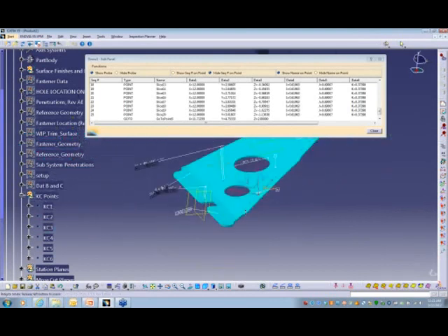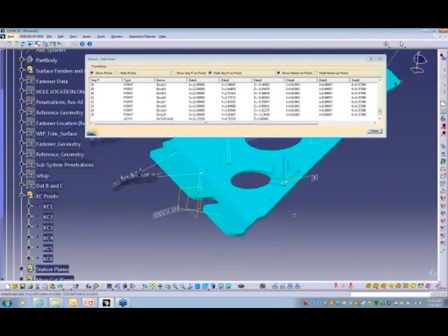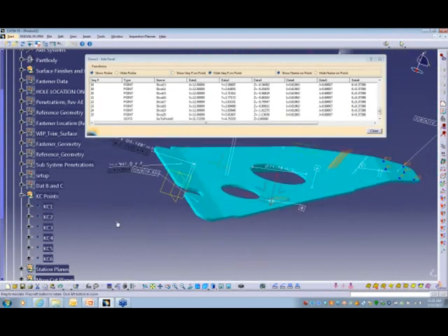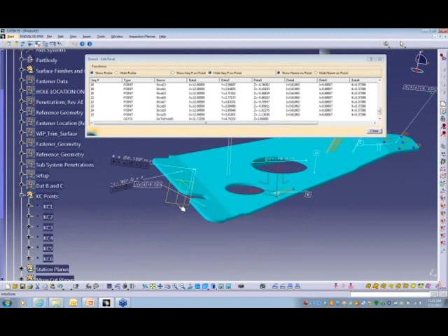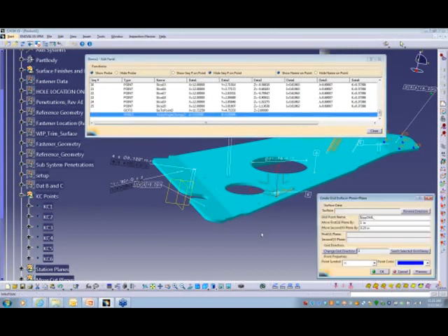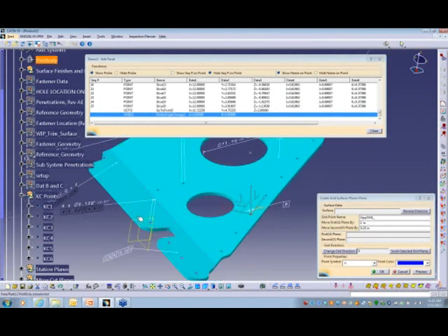And we're going to inspect this surface right here, and we have some more planes that we want to cut that part from. And you can see you can't really align the points to the UV. We want to align our grid of points to these planes. So we have another feature that we can use, and we can say we want to put our points 1 inch in this length direction, and then 1/4 inch in this direction. We can set our name, so we can call that upper OML.